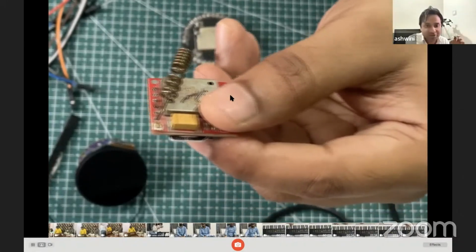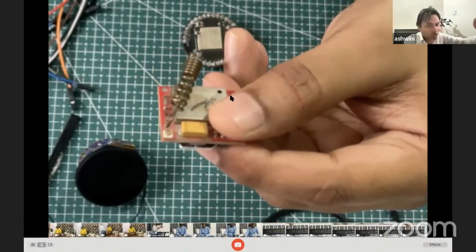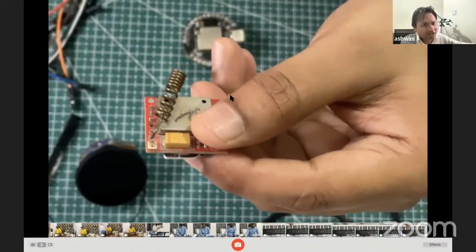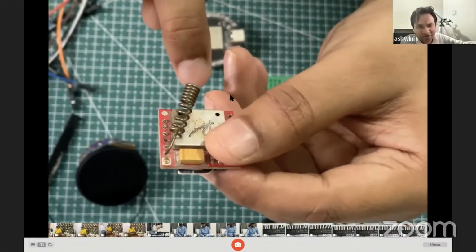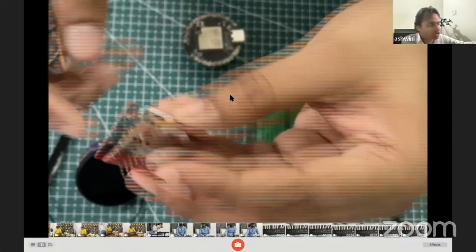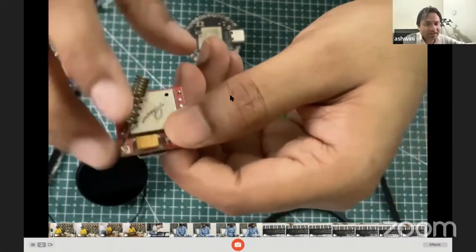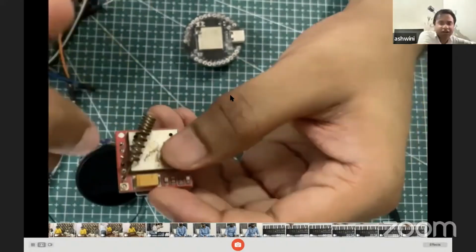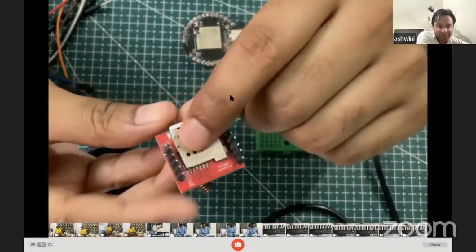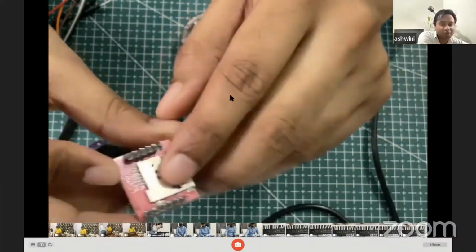So they are hidden behind the phone body. In older phones, you might have seen those long antennas coming out of the phone. So it is that kind of antenna. If you want to use this older kind of antenna, it comes free with this module. Then you can add it and solder it here. Otherwise you can leave it. So these are the pins for communication and powering, and these are the pins for the other functions.